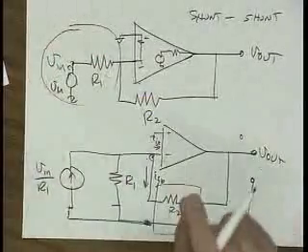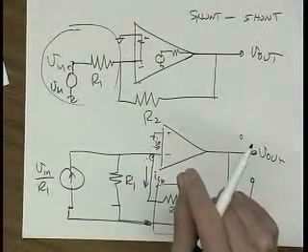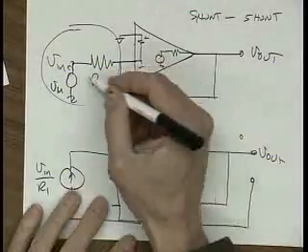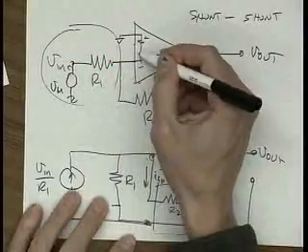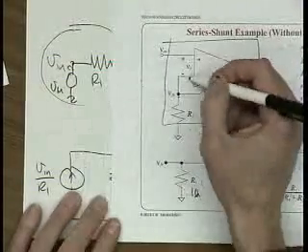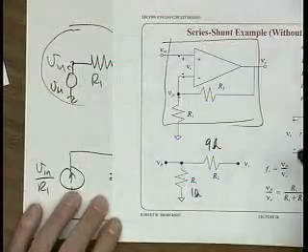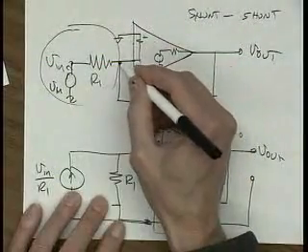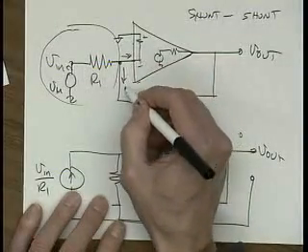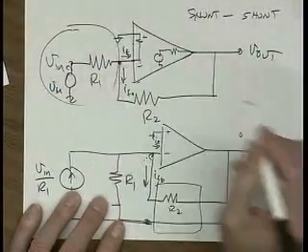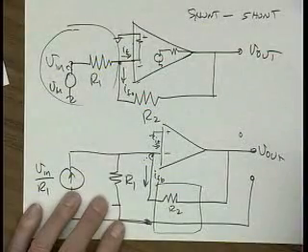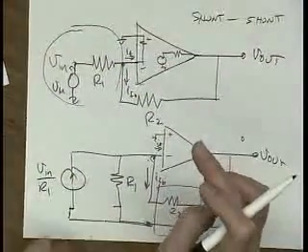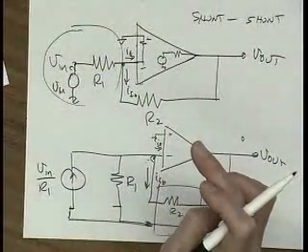The trick is to find out where the differencing is going on. Find the node where there's a difference. Identify the error. See, there's no error voltage being developed anywhere here, right? Here I had an error voltage being developed by this minus this. But here there's no error voltage being developed. Something's happening on this node here. It's a difference occurrence. Here's I feedback, and here's I error coming in there. So it's a feedback current. Okay, see that?